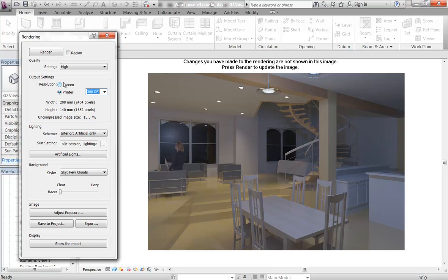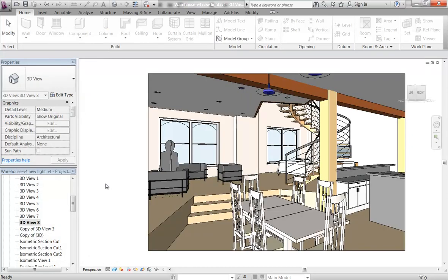Well, that's actually still fairly large for a full rendered image, an A3 size rendered image, because you've got to remember, they'll often be on a board with several other images and other graphics and text and things, so the actual rendered image may not be that big on its own. But you might have 1 or 2 that are, say, A3 on their own on a board. So say if you need to do that, like the big feature image, the way you do it is first to set the size. So you might have noticed there's also the size in millimeters there. Now, I'll go and show you an A3 image, but I'll do it with a different view. So I'm going to close this dialog for now and just go into a different one.